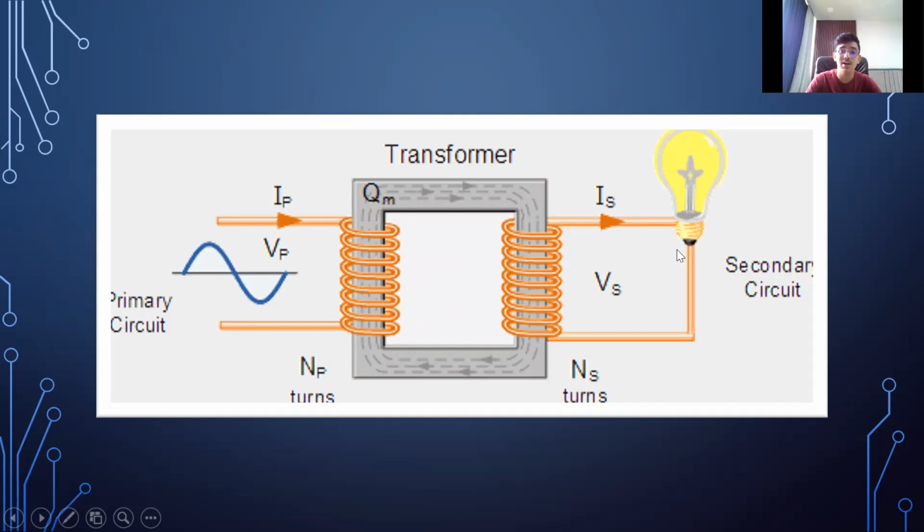What did I say earlier? 3 volts. So 1/4 equals 3 upon x. You need to cancel that out. You get 12, as you need 12 coils in the secondary coil to get your final voltage as 3 volts in the bulb.